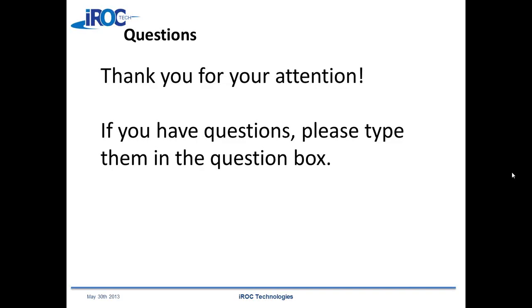Common sense says you don't want the number one cause of field returns of your product to be soft errors, because that's a cost you don't need to incur. So if you can keep the field return rate due to soft errors a step below, whether that's an order of magnitude or a factor of 2 below the field return rate due to other causes of failure, then you've made sure that soft errors aren't the weakest link in your reliability chain.